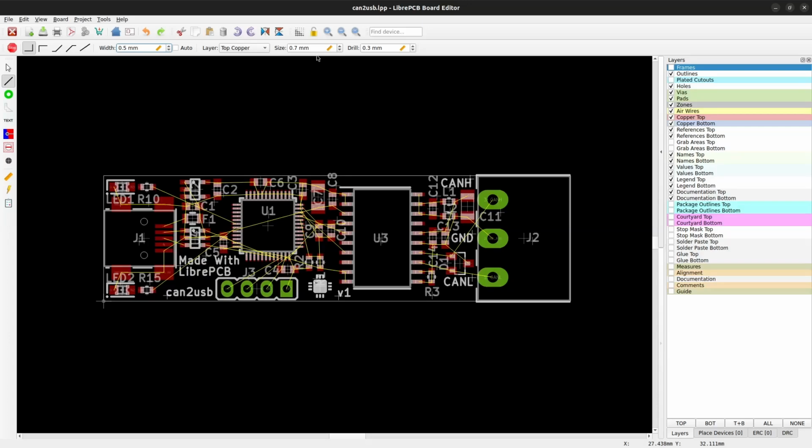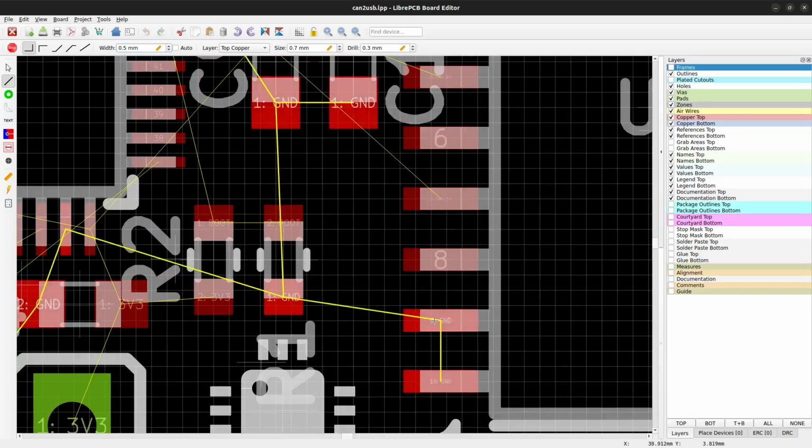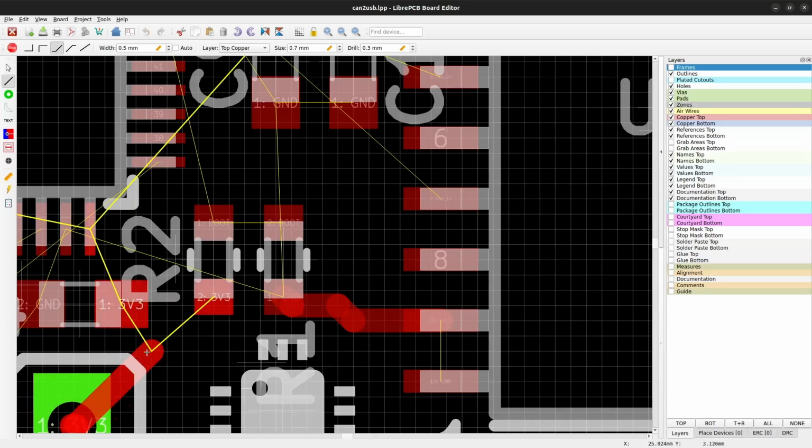As already known from the schematic editor, start a trace by clicking on a pad, use the right mouse button to switch between different routing modes, and add more vertices with the left mouse button. A trace is automatically finished when ending at a pad or within another trace. Note that the cursor automatically snaps to footprint pads and trace vertices to support making connections outside the grid interval. If this is not desired, hold the Shift key to disable snapping.